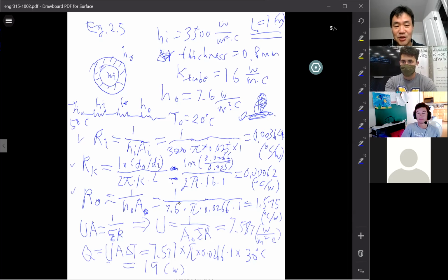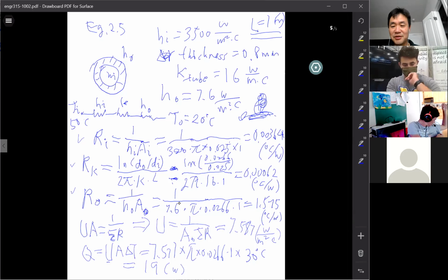I think delta T over thermal resistance is totally correct in whatever situation. That makes sense? Any questions? But I really want you to know both, because in practical applications people use UA delta T a lot.